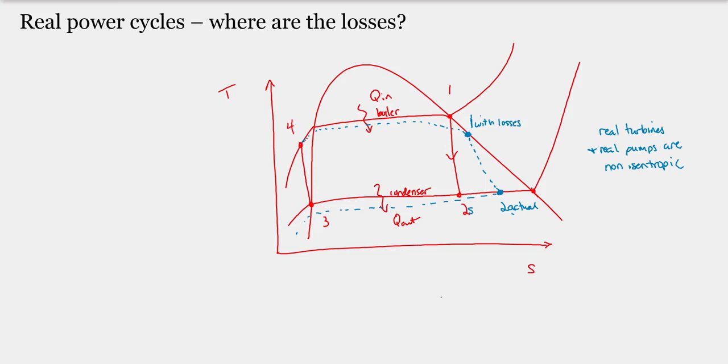Okay. And nominally, you're not going to lose pressure below the ambient, right? Because at that point, you would potentially have ambient gases leak into the system. So this is probably limited by the ambient pressure. So you'd run your condenser at slightly above atmospheric conditions. Okay. And then again, we're going to target that the exit condition has to be a fully saturated liquid.